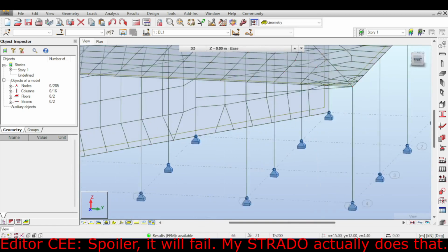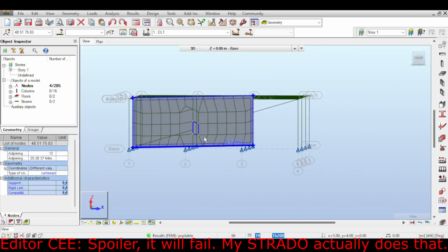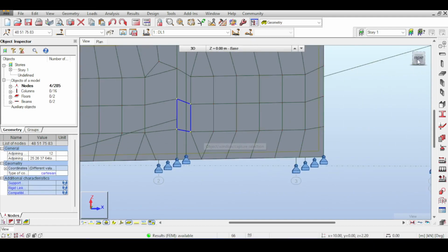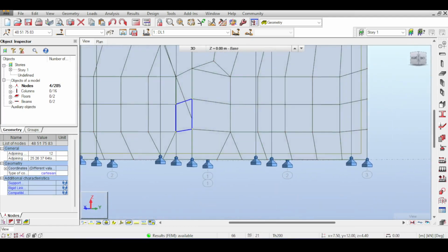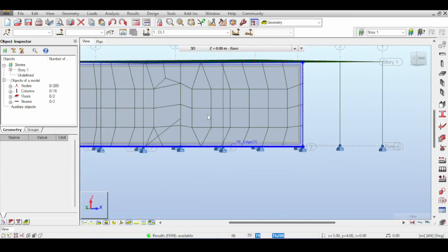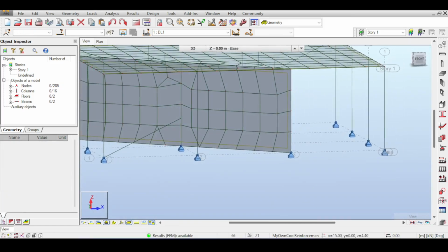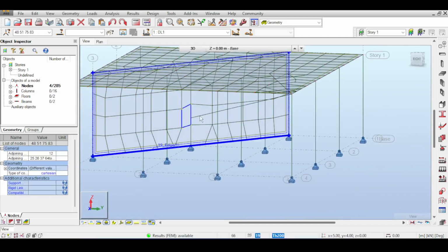Wait, what? It didn't find it? Huh. That's surprising. It's a failure in meshing. It should not be like that. Well, I guess I found a point where I am doing better than this. It should have... That's strange. I'm surprised. The mesh is now incorrect, by the way, because you have an element here, as you can see, and it doesn't connect with this element, meaning that the beam doesn't feel the wall here, and the wall doesn't feel the beam. There is no force exchange between them.